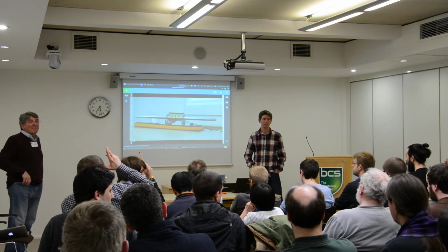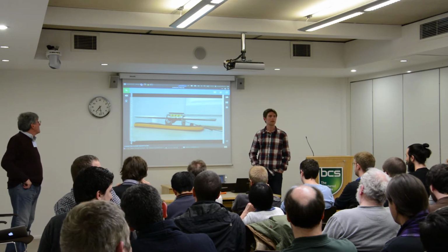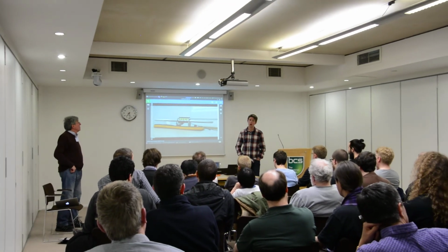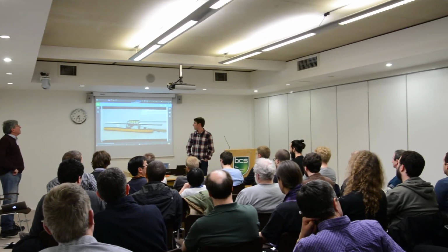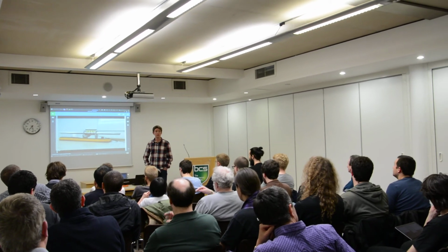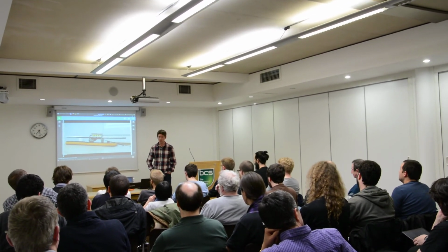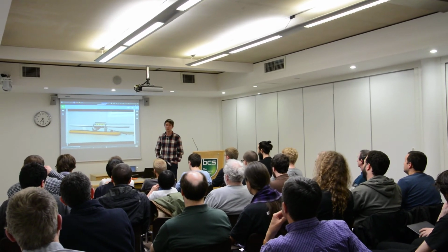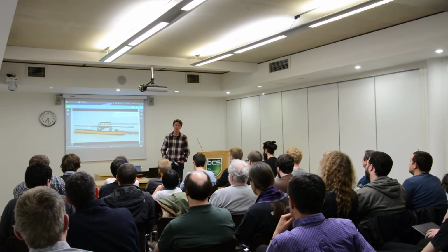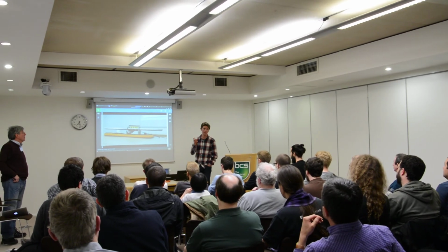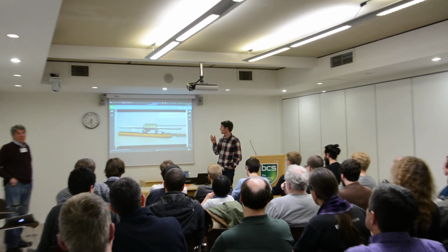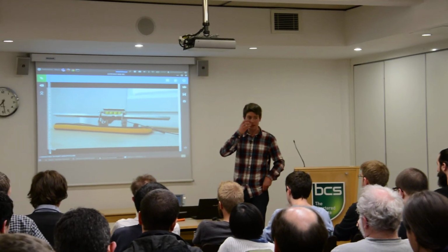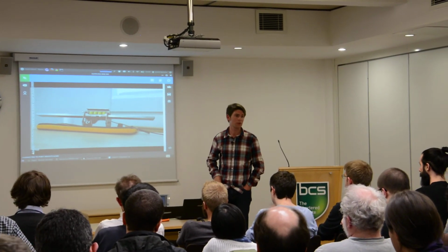You showed an ARM example there. Do you have it running on small AVR chips as well? No, I don't. Is that feasible? Yes, there's actually no ARM assembler in it at all, so it's quite easy to compile. It was originally meant to fit on a 4K RAM PIC part, which is why things are done in a way that really crams the memory down. So it shouldn't really be a problem to port over.